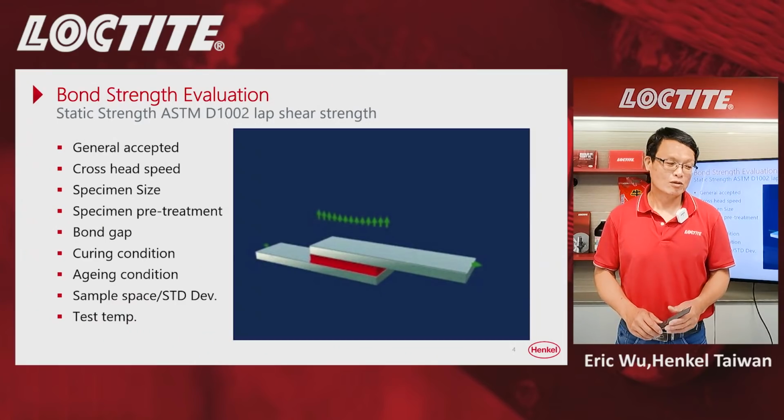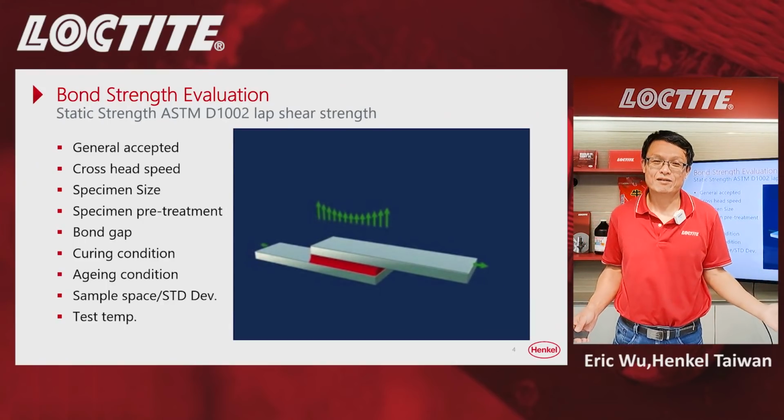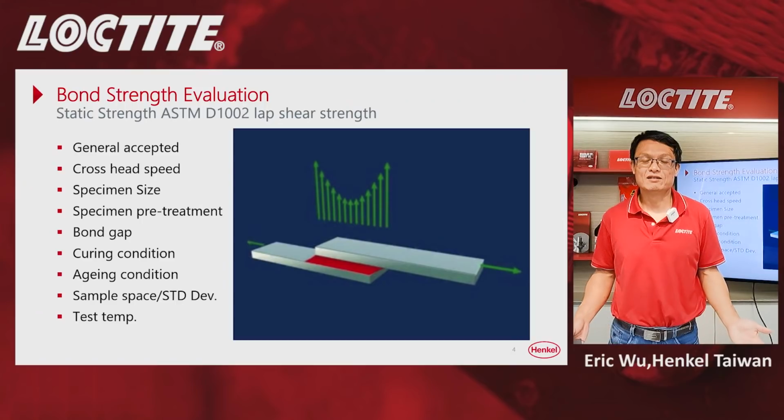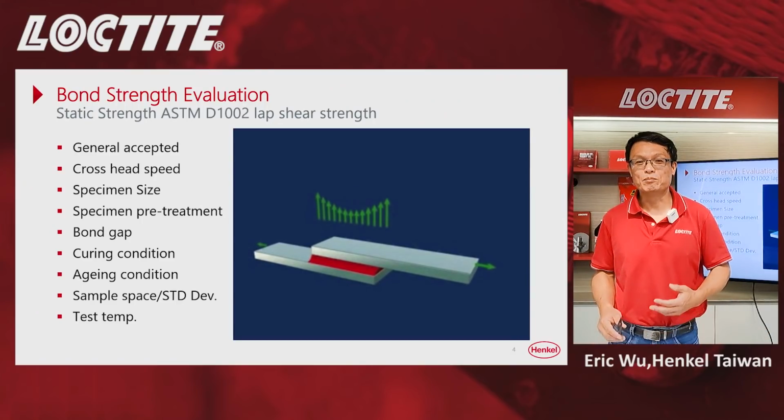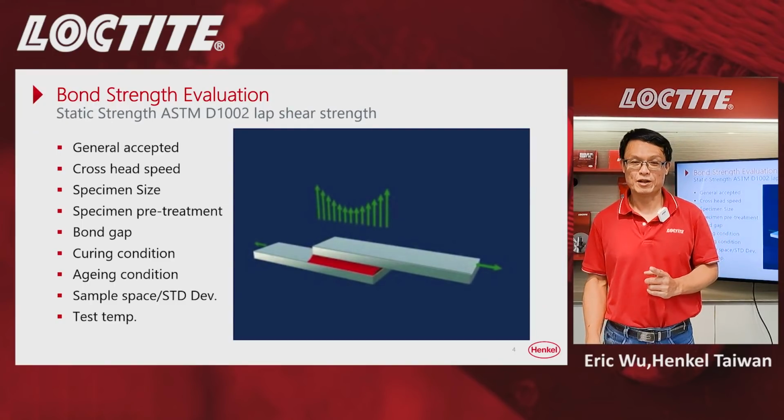This is the actual load applied to your structure, like a sports bike, an aircraft, or any kind of transportation vehicle. The loading applied to the product you design is never a static one. So this data gives a challenge to the design engineer. You can't use this data. Even though it is provided by the supplier, the data is not meaningful to your design. So this is the first challenge we introduce here.